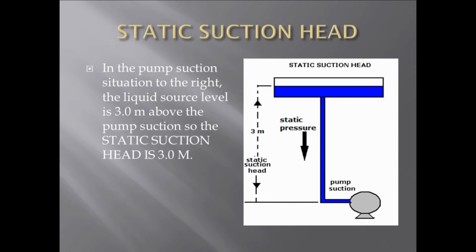In the pump suction situation to the right, the liquid source level is 3 meters above the pump suction, so the static suction head is 3 meters.